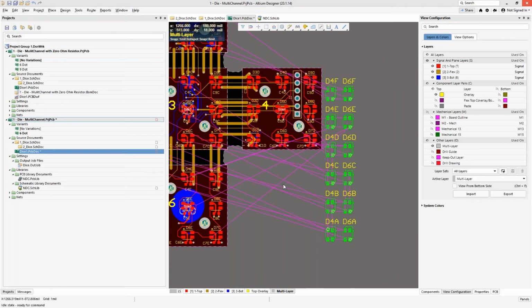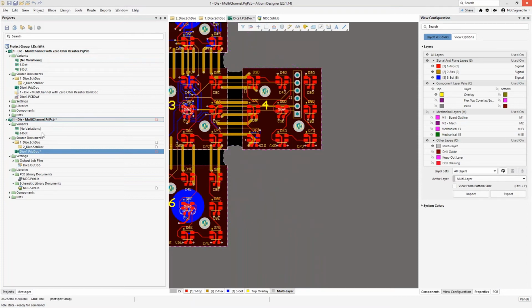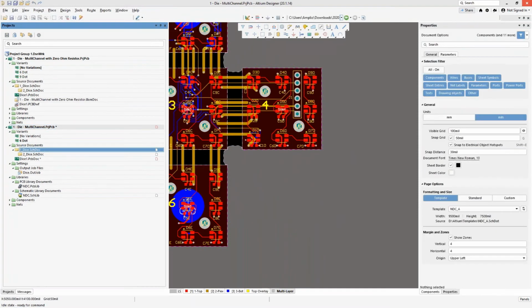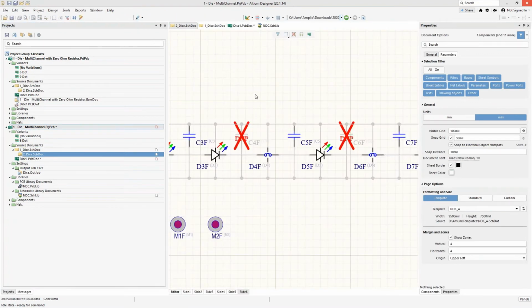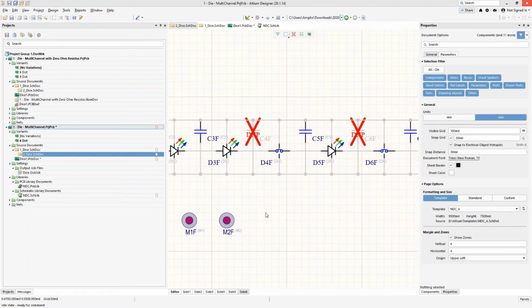There's one other thing that I'd like to show you, which is really important to note, especially in a multi-channel design. So I'll just do a Control Z here to remove this. But let me go back over here to my design and show you a few things that are really important, especially with multi-channel. So in a multi-channel design, when it comes to fitting or unfitting a part, you can do it to any one of the designs, and Altium is going to be okay with that.